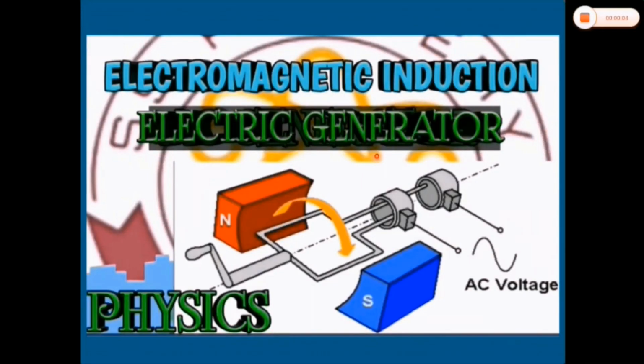Electric generator. An electric generator converts mechanical or kinetic energy into electrical energy. Two fixed strong permanent magnets are placed with their opposite poles facing each other. The magnetic field is concentrated onto the coil by the soft iron structure, which is curved inwards. Both AC and DC generators work on the principle of electromagnetic induction and are essentially electric motors working in reverse. An alternating EMF can be induced by rotating either a coil in the magnetic field or a magnetic field within a stationary coil.